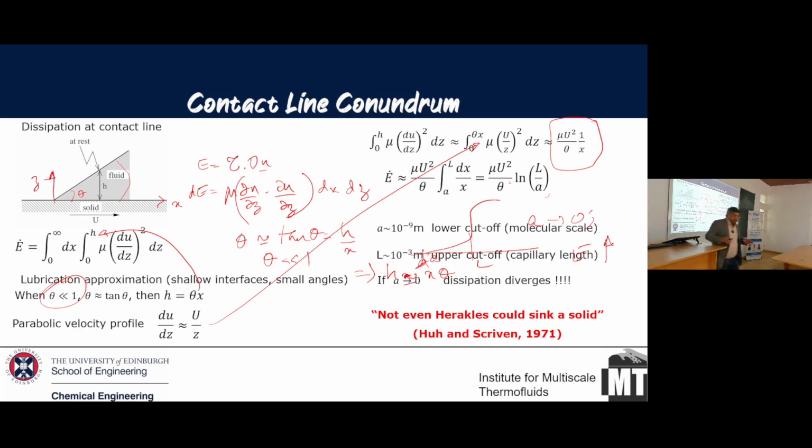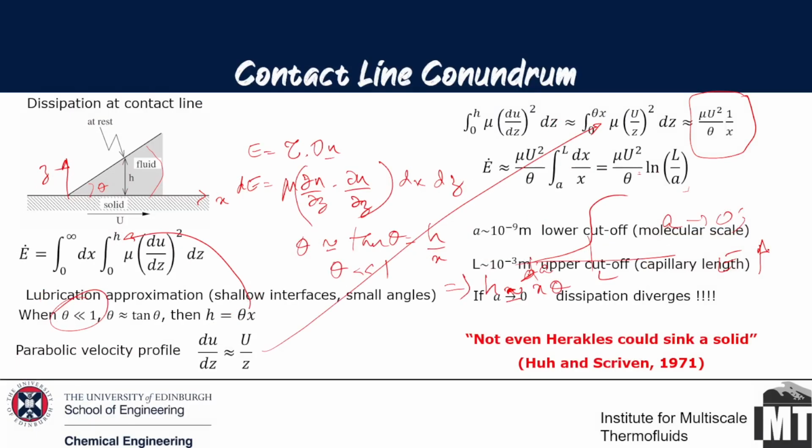Yeah. Why does wetting have cos theta, not sin theta? Which one? Sorry. So why does wetting have cos theta, not sin theta? It's because you can have sin theta as well. It depends upon the angle and side you're taking. It's up to you. But typically, when we do a force balance on the surface, we take the horizontal component. If you do a vertical force balance, then you will get a sin theta. So it's just a matter of direction.